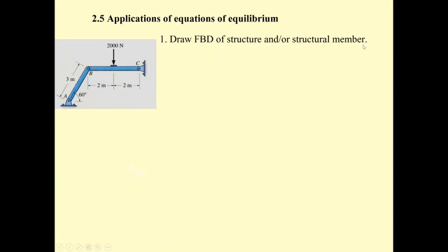Anyway, unstable structures also have other types to be considered. One is parallel forces. Another one is concurrent forces. With these two types, even though the unknown reactions equal the number of equations of equilibrium, the structure is also unstable.